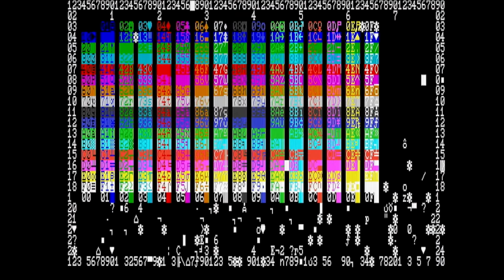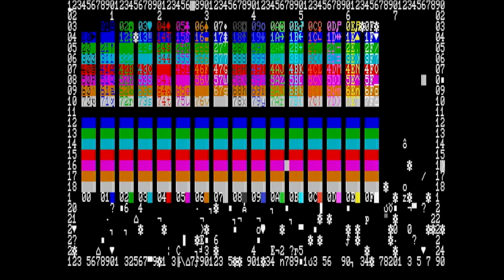So we've now got the clear screen, so I'm just going to press the key each time and we'll see what results we get. You can see that the mess at the bottom there seems to indicate that there is still some sort of issue here, but the top part's okay. It might indicate there's some problem to do with the higher area of memory. Perhaps some of the address lines and things are messed up. So we'll have a look at that in a bit.